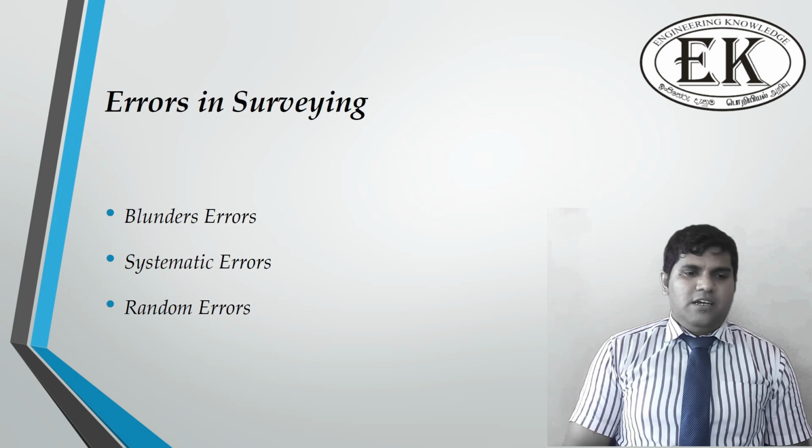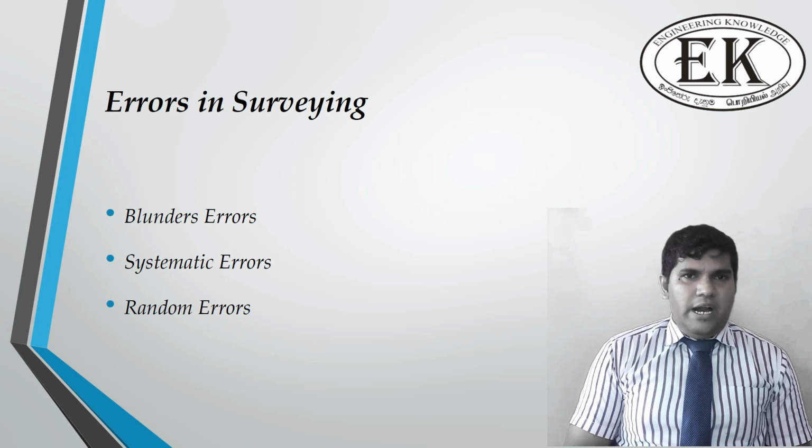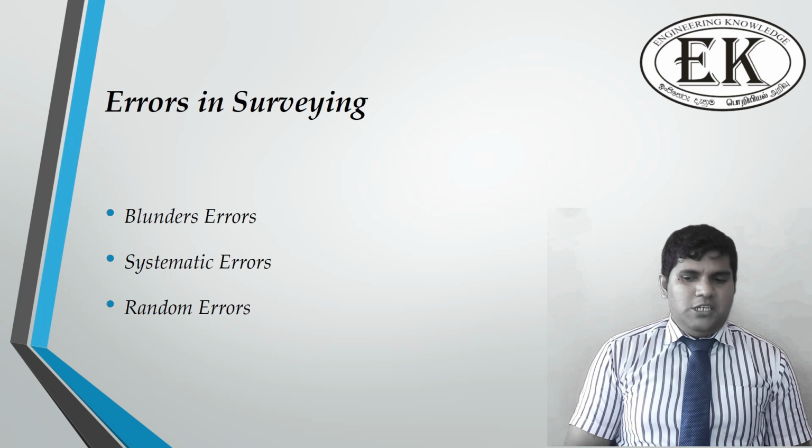The second one is systematic errors. These systematic errors are again grouped into 5. The first one is standardization, then temperature, pull and sag, and the last one is slope errors. The third one is random errors. When we are doing surveying, some errors will occur randomly, and that comes under random errors.